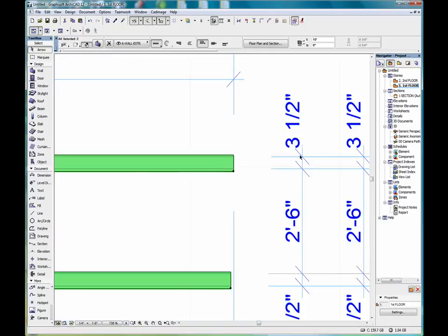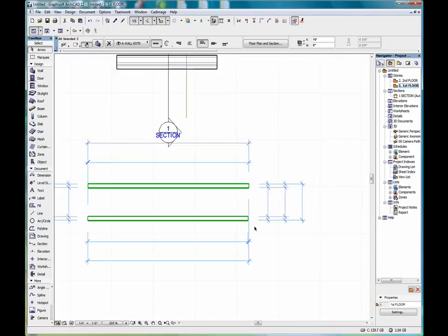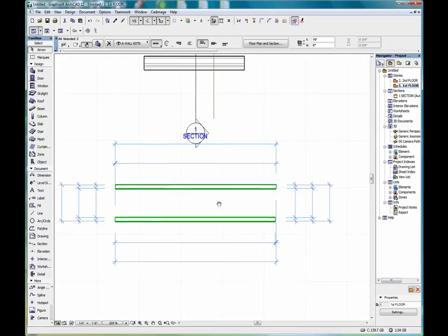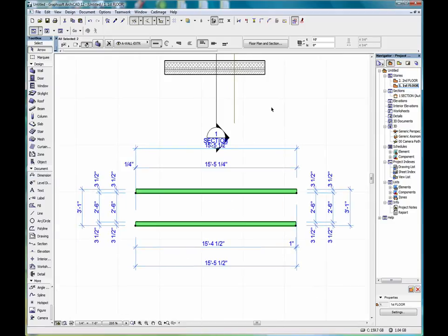You can see that with the automatic dimensioning, the dimensioning is picking up the core structure for the dimension value of 3.5 inches and not the outer or inner skin. So that's one way the core and finish tabs on our selections for the composite work in dimensioning in ARCHICAD.